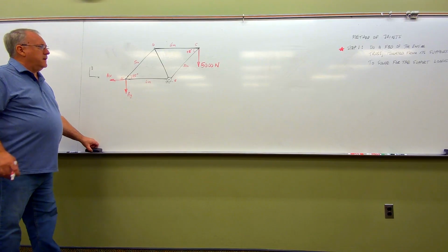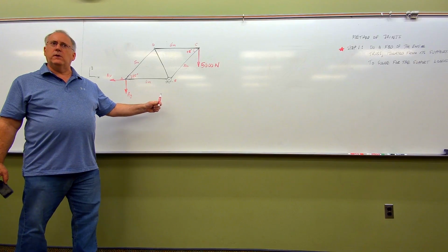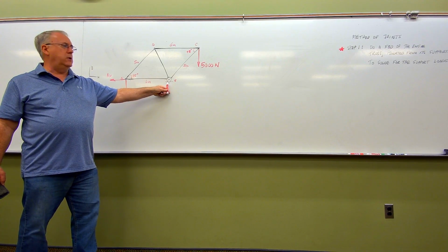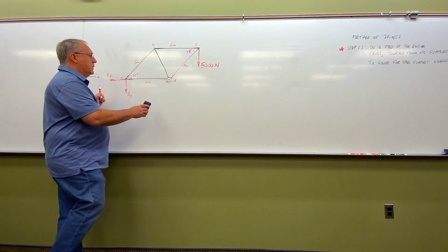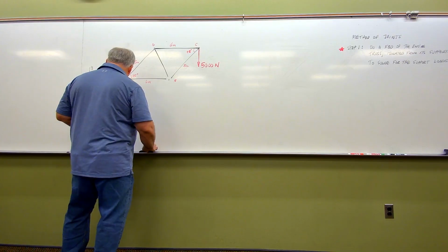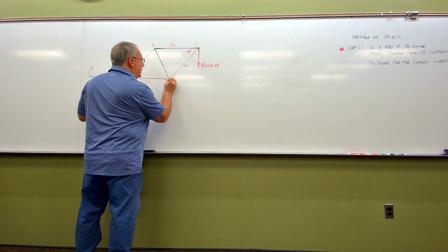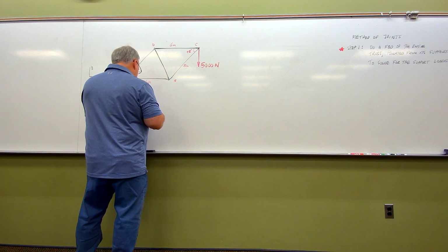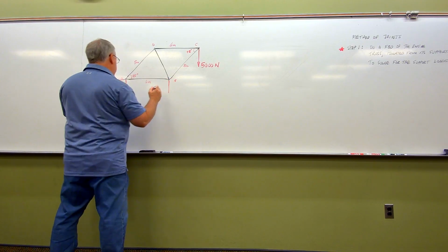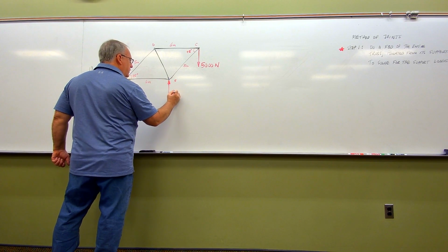And then lastly over here, I'm going to have the force on roller B. And again, we already know from what we learned back at the beginning of chapter 3 that forces on rollers are singular forces drawn normal to the plane of contact. So in this case, I can get rid of all of this. Again, I want to make this look like a free body. Bring this together though. And now as far as the force here on B goes, again, roller force, single force. Since I threw this one downward, let me take a guess that this one here is going upward. And I'm just going to call this force, force B.